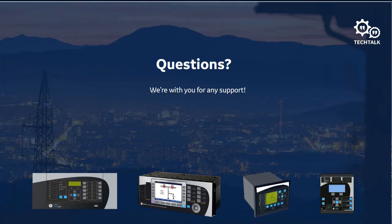Similar things with negative sequence. It's a little bit more complicated than the zero sequence, where you just got to sum the three. Basically what you're doing is you're wiring the three CTs in parallel and taking that parallel connection out to the ground relay, and that's how you would sum them and build that zero sequence.